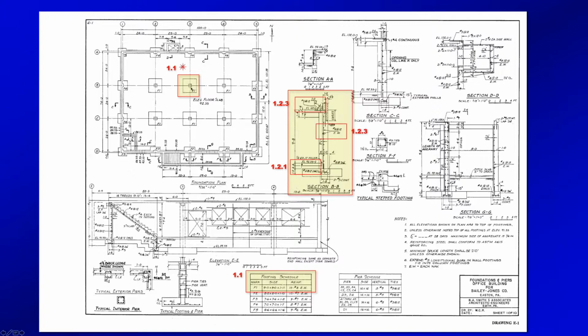And rebar number and size. Oh, and what is the size of the footing? So how do you find that? Well, you have to go find the footing schedule, for instance, down here, which is marked F1. And you can see that that's a 9 foot by 9 foot by 1 foot 11 inch deep footing. Who in the world? That sounds like an engineer, doesn't it? We're going to pick on Luke for a minute. Luke, would you design a footing that was 1 foot, 11 inches deep?